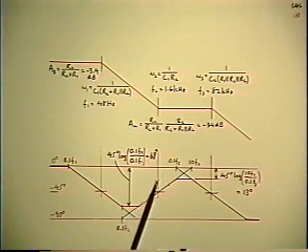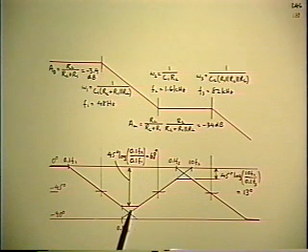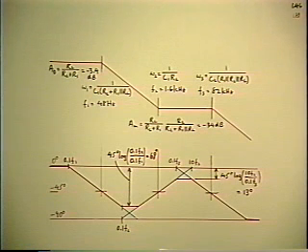Notice that with the numbers we get phase overlap such that there's a phase lag of 68 degrees over this particular frequency range. Now imagine that the design problem is you want to prevent the maximum phase lag from exceeding 50 degrees at any frequency. Change the values to achieve that.